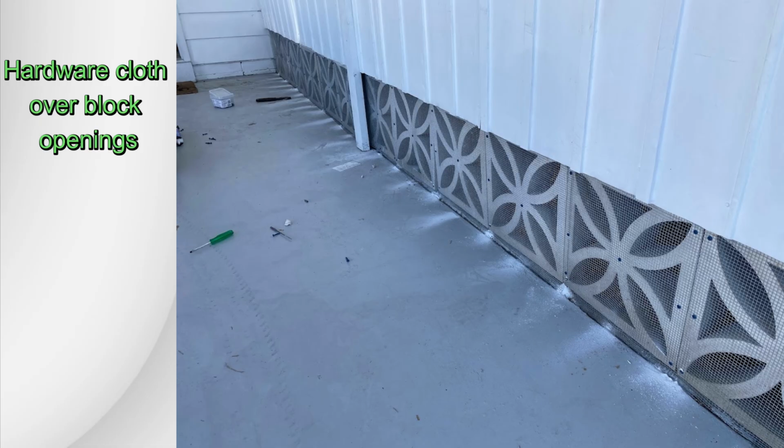At this point, we would just put a hardware cloth over it, which I'll show you in the next image, but I think hardware cloth is a good way to exclude big openings like this. You could also use sheet metal if the openings are on different types of structures, different areas where you don't need air movement to come through, but definitely like a crawl space where you need air movement, hardware cloth is going to be the best way to exclude these areas. Looking back at what we showed you in the previous slide, we actually went over those open snowflake block openings with hardware cloth.